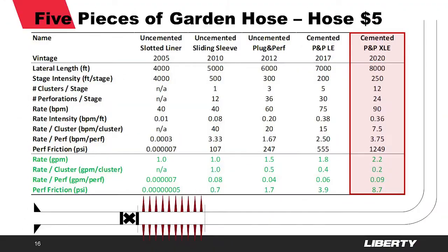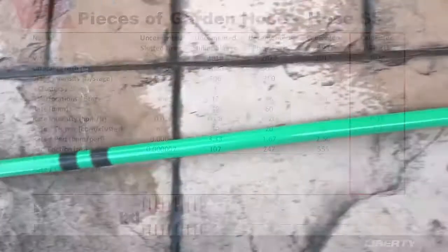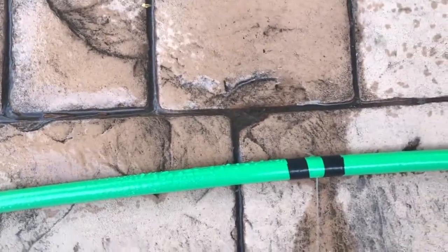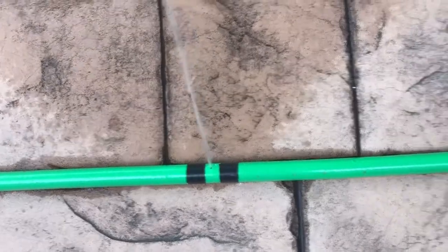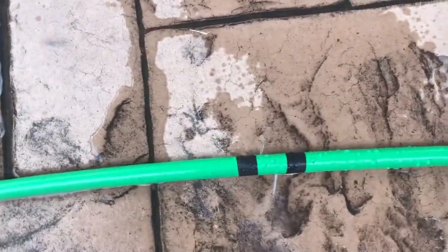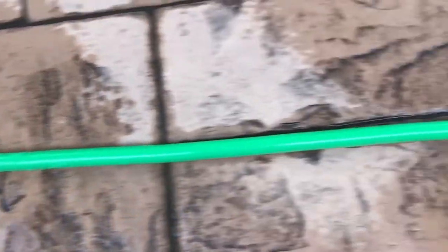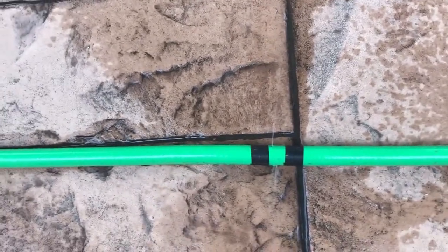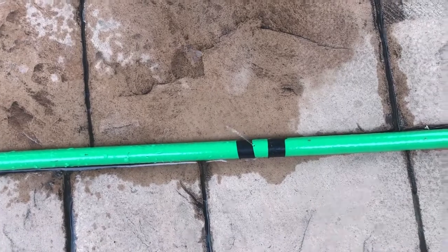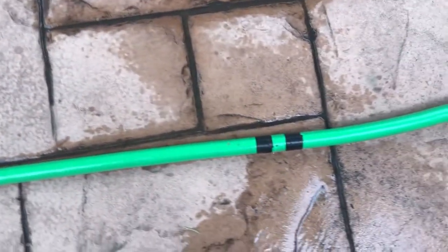More recently, some operators, for example Liberty Resources in the Williston Basin, have tweaked this approach to create more fractures per lateral foot of wellbore. Well design number 5 features a higher rate per perforation, more clusters, but fewer perforations per cluster. This results in more extreme limited entry perforation friction pressures to improve cluster efficiency and better distribute frac fluid volume and proppant mass amongst perf clusters.